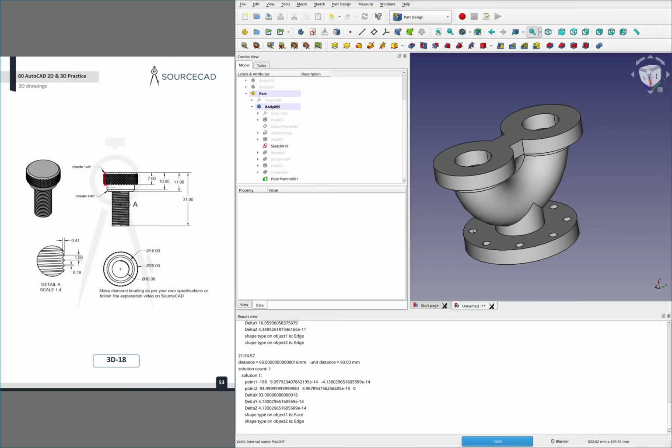It is just one big sketch, which is then revolved around, and then you put in a helix, right, with these dimensions here, and then you model some of these other dimensions, and then you use the cut helix button up here to cut that into the shape. Overall, straightforward.